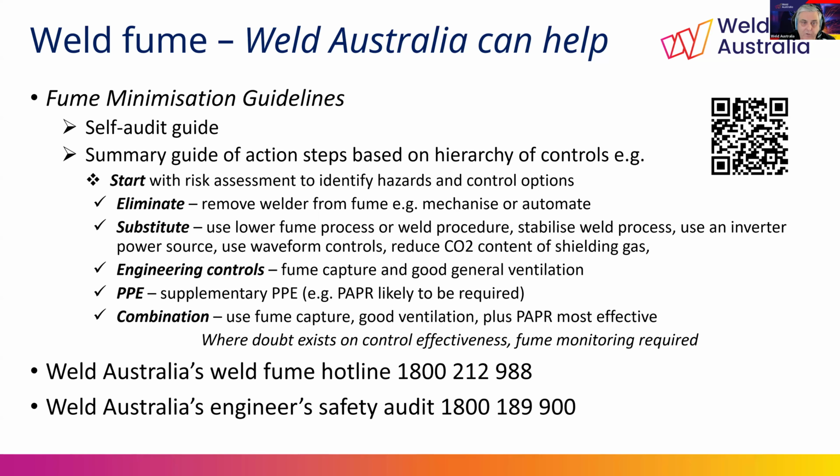Now, powered air purifying respirators, we know, are highly effective to protect welders and especially from excess ozone exposure. Now, fume capture devices are generally ineffective against ozone because ozone forms wherever there's UV. PAPRs, though, it doesn't matter where the ozone is. The PAPRs draw air from behind the welder, and as a consequence, there's not much UV in that area, and so there's usually very little ozone present in that area, but you can also add a filter if need be to filter it out.